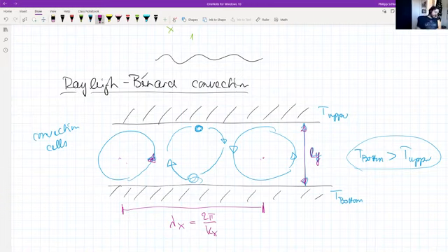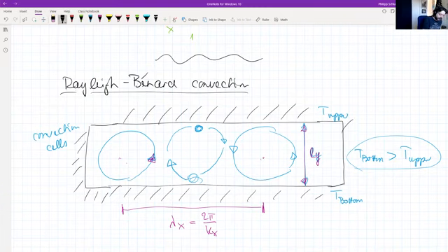So essentially, this is the case that we would like to simulate. Now, we have a slight issue with the code that we're going to implement. Namely, we would be able, but it's not implemented in that way, to have infinite boundary conditions. So what we do is actually we set here on the side also a solid wall, and also here we set the solid wall.